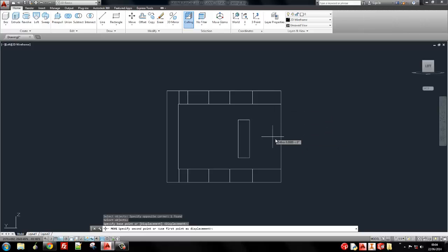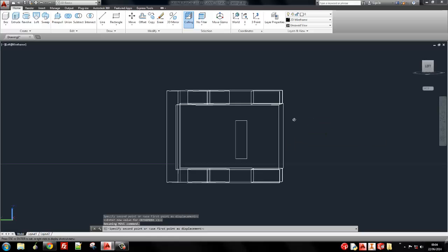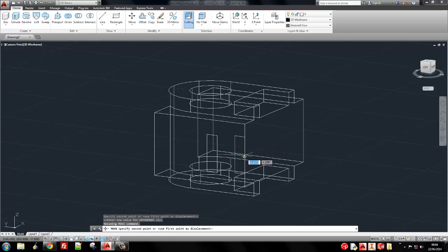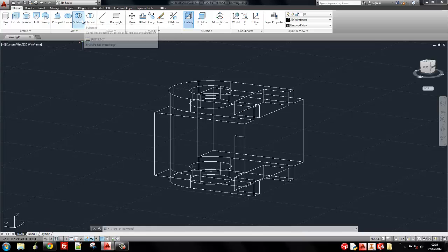Now, when you do move it in this way, because I'm looking dead on the left orientation, you have to be a little bit careful that you're not picking the back face of the shape rather than the front face. So sometimes it is worth just rotating your screen to make sure you are picking the right face. I suppose in this one it doesn't actually matter because we could just extrude it the other way, but for later reference, if you wanted to do that, that's how you would do it.